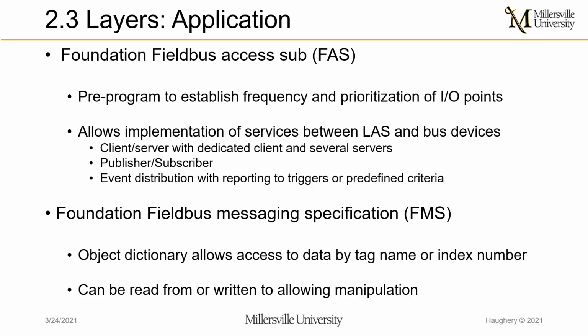It also has a messaging spec, where there's an object dictionary which allows access to data by tag name or index number, and can be read from and written to, which allows manipulation of the tags on the Fieldbus network.